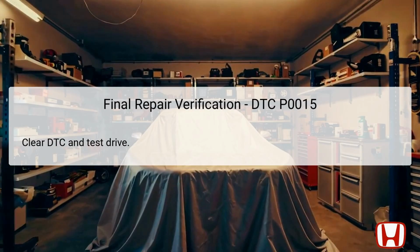After performing all necessary repairs or replacements, it is crucial to conduct a final verification to ensure the DTC P0015 has been resolved. Begin by using the diagnostic tool to clear the fault code from the PCM. This step allows you to reset any learned behaviors that the PCM may have adapted while the faults were present.